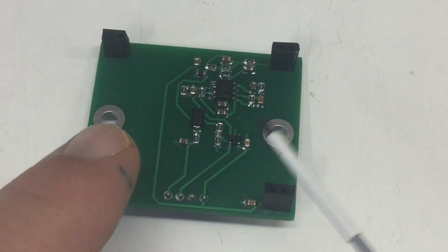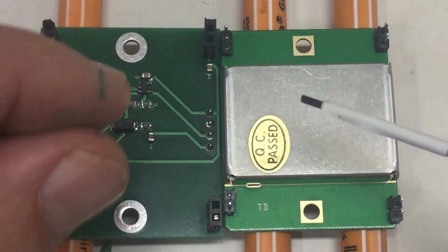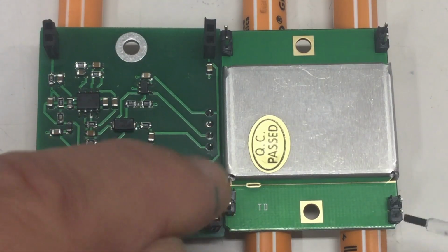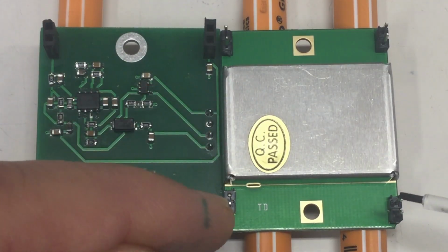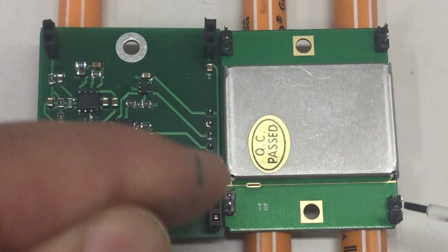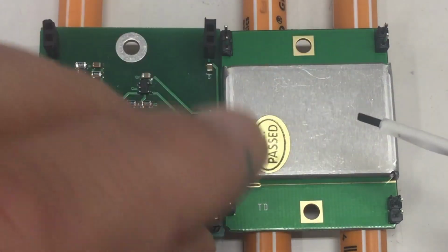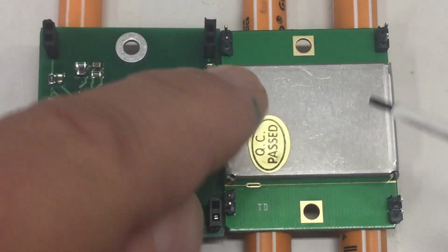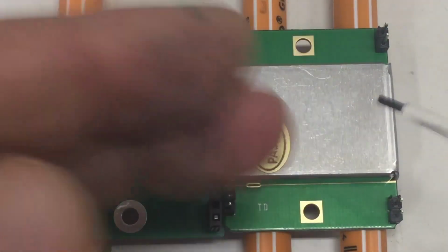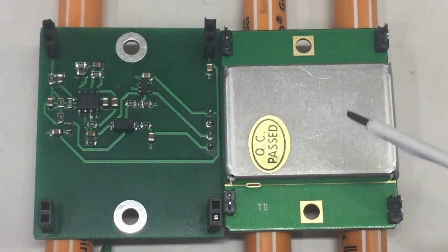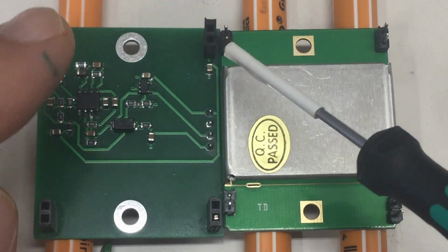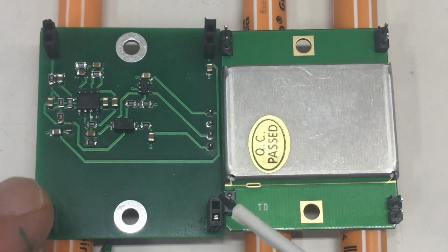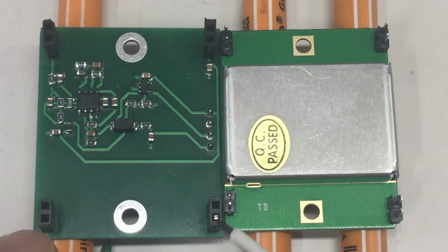But there's a little problem. Remember how I told you that the ground headers on the HB100 are offset 0.1 inches to each other? That's of course to prevent the HB100 being plugged in the wrong way around in whatever breakout board you are using. However, on Limpkin's breakout board there is no such offset on the ground headers.